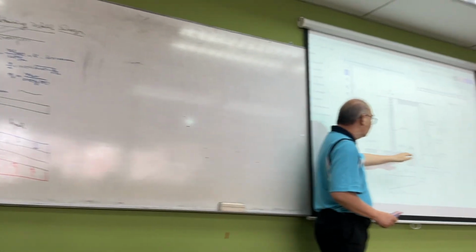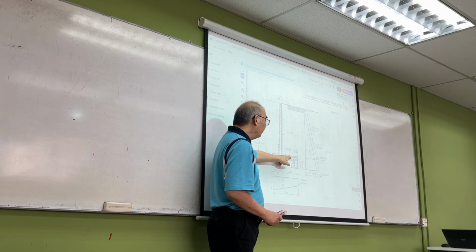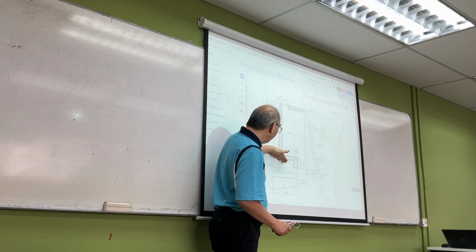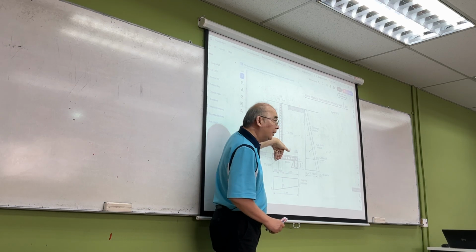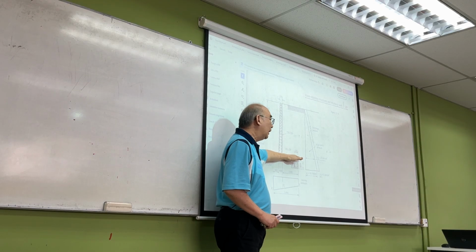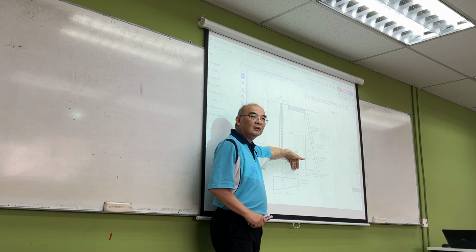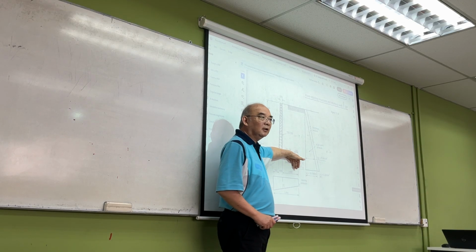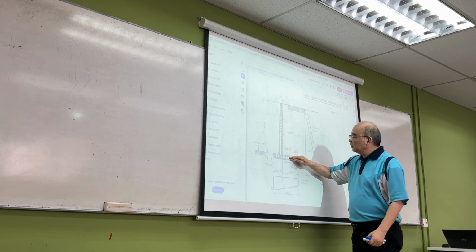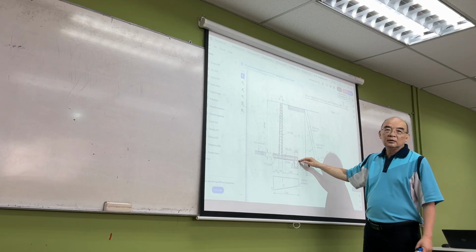So the base slab, you have the top reinforcement and the bottom reinforcement. The bottom reinforcement basically carries the upward bending moment from the toe. This one is carrying the downward bending moment from the soil. And then this one going in is temperature control.